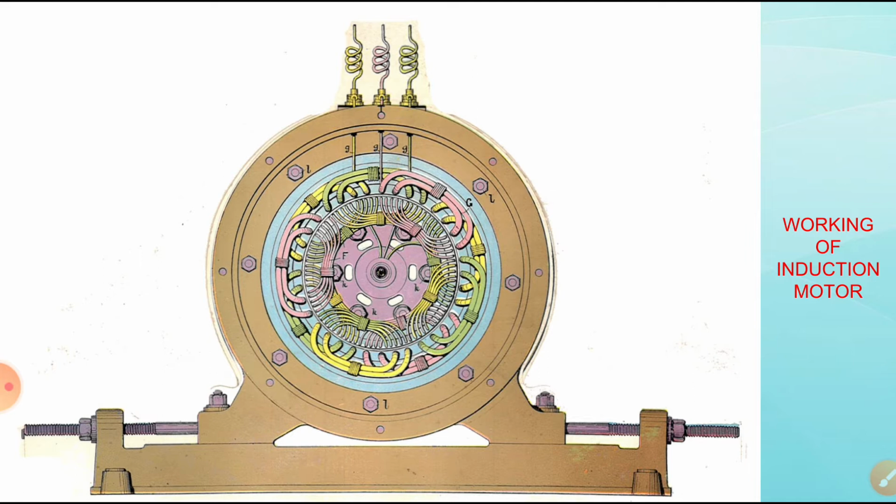These induction motors can operate in any environmental conditions. That is, induction motors can be operated in polluted and explosive environments as they do not have brushes which can cause sparks like in DC motors.